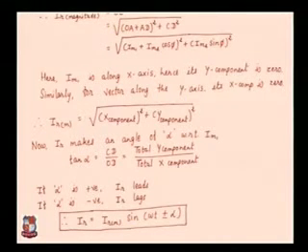So if you solve this equation, you get the magnitude of the resultant current. So this first bracket indicates the x component of current and the second bracket indicates the y component of current. So you can rewrite this equation like this. IR magnitude is equal to under root of x component square plus y component square. Now this will give you the magnitude of the resultant value. If you have to find the phase angle of the resultant current, then the equation is like this: tan alpha, where alpha is the phase angle, is equal to y component divided by x component.